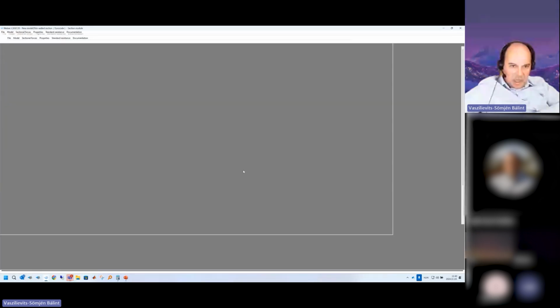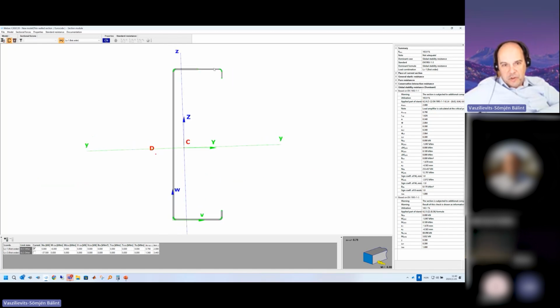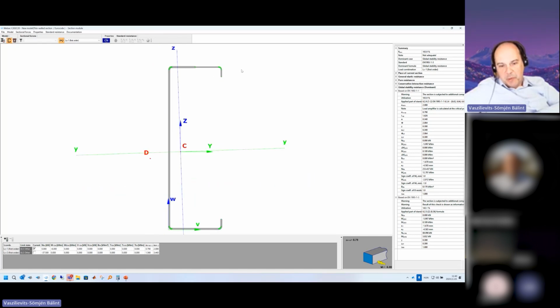And as I said at the beginning, the design will already call the usual single profile. So this is not the single profile, double profile anymore, but the single profile. The internal forces have been prepared by Consteel consistently on the single element, and on the single element we can perform all the structural design verification as required. For the bending condition, we see that we have compression on the top flange, and there it was required to apply a thickness reduction due to distortional buckling.